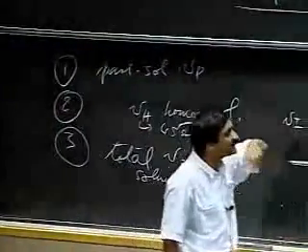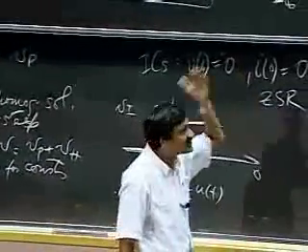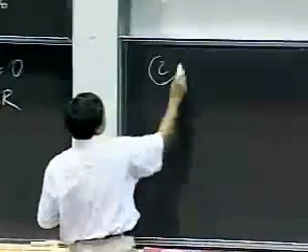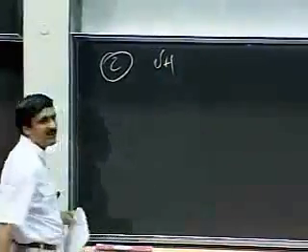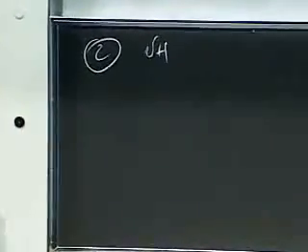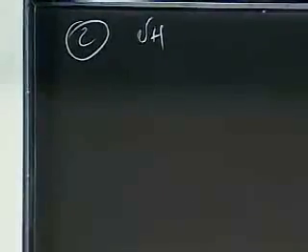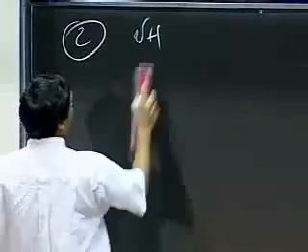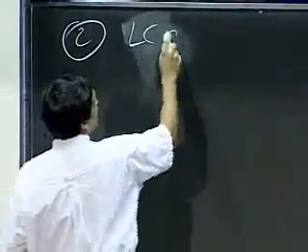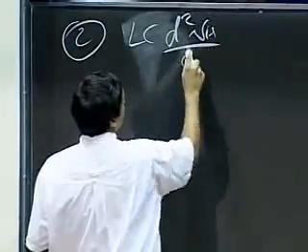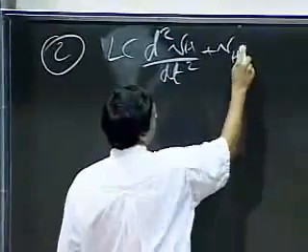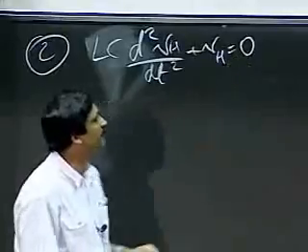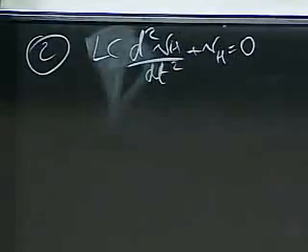So I've done my first step. I found the particular solution, and Vi is a good enough particular solution, so I'll use it. I'll take it. So as my second step, I'm going to find VH, or the solution to the homogeneous equation. And the homogeneous equation is simply that equation with the drive set to 0. So what I get here is LC d squared VH dt squared plus VH equals 0, so that is my homogeneous equation. I simply set the drive to be 0. And to find the solution here, I go through my 4-step method.